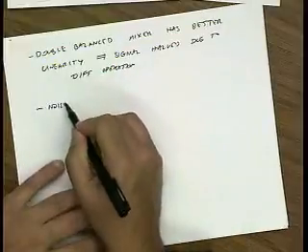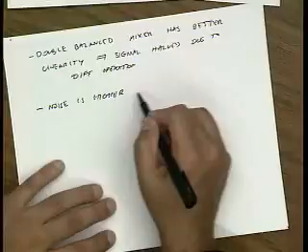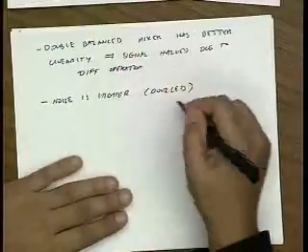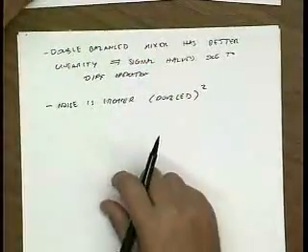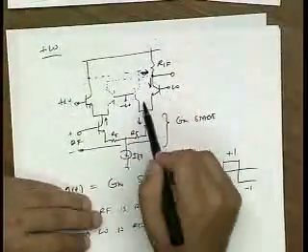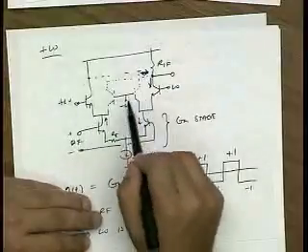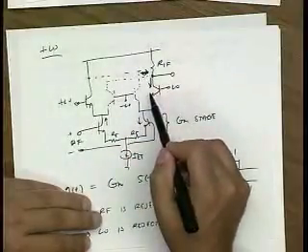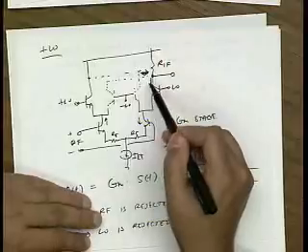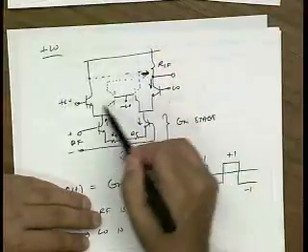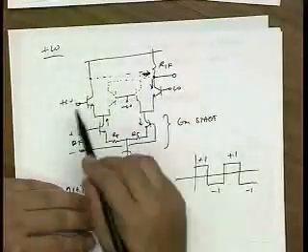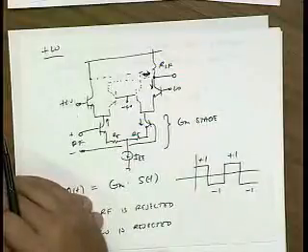The noise, on the other hand, is unfortunately doubled, actually quadrupled if we take into account the square. And that's because even though I can reject my LO signal, the noise on the LOs is not correlated. Because the noise of each transistor is independent from the noise of the other transistors, these signal currents cancel out, but the noise currents add in quadrature. And so the noise of these two stages adds to the output. So here it's even more important to have a very large swing to try to reject the noise coming from the LO port.